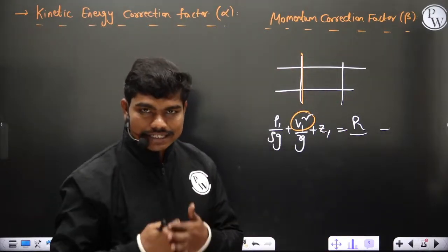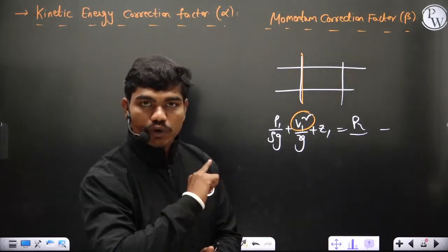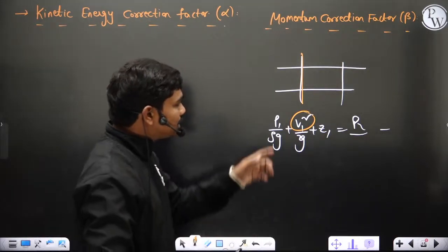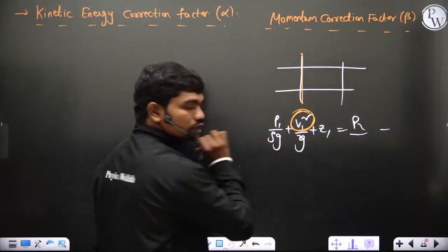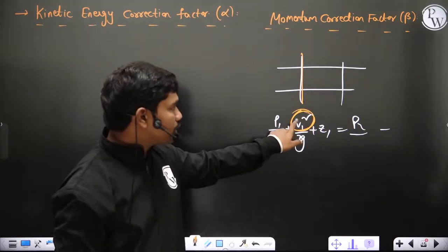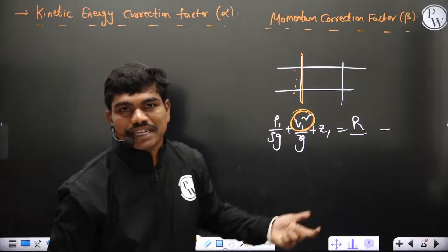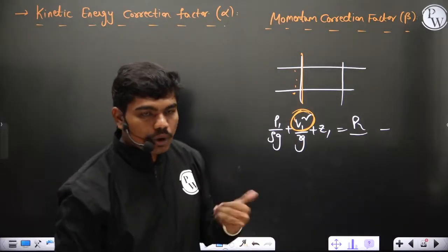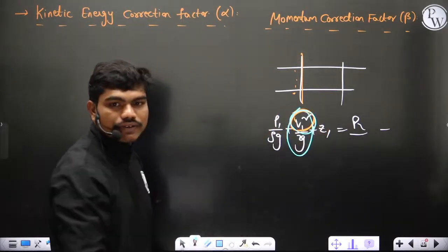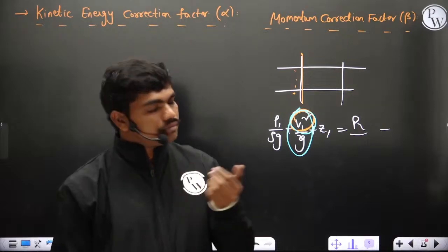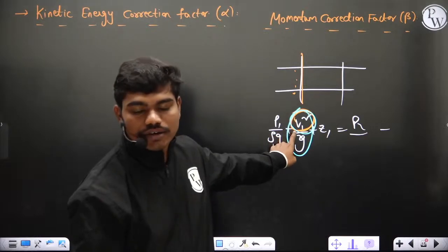But later you recognize there is viscosity in the fluid, and the viscosity will not allow all the layers of the fluid to move with constant velocity. So in this expression, in which you neglected the viscous effects, you have to change this V1. Yes or no? Clear? This V1 which you are substituting, which you are assuming to be uniform at every point in this section, is not a very considerable assumption. Therefore this V1 or this kinetic head requires some correction. As you know, these are factors, so you have to multiply certain factors to make this expression suitable for the actual flow conditions.